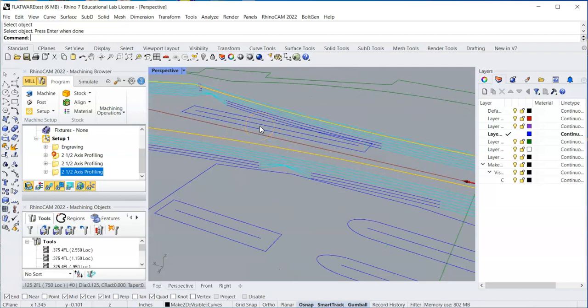I have had it though, where if you've got a large enough thing that you're taking out of the middle, where you do want to put bridges, because otherwise, when it gets done, even though that's a part that's going to be removed, I've had it where it's been cutting it out, and if you don't make sure that thing is secure, it'll hit the bit and ricochet off of it, and usually catches the bit between the wall of the piece you want and the piece that you don't want, and it cracks your bit and breaks it.